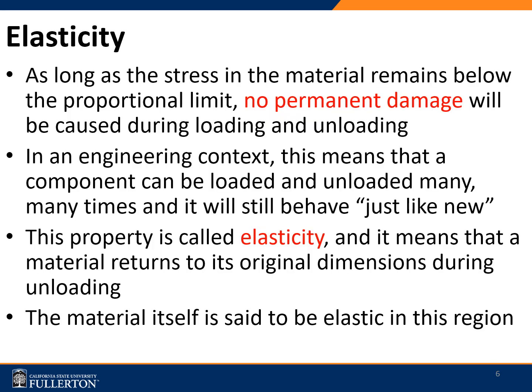So what is elasticity? Elasticity is the behavior of the material to return to its original shape or dimension after the load is removed. The material within the elastic region does undergo deformation. However, once the load is removed, it doesn't show any evidence of permanent damage. And that's the importance of elasticity. Beyond the elastic limit, the material tends to accumulate some amount of permanent damage.